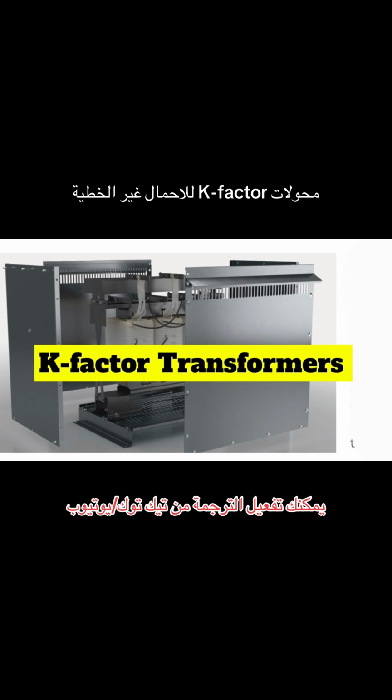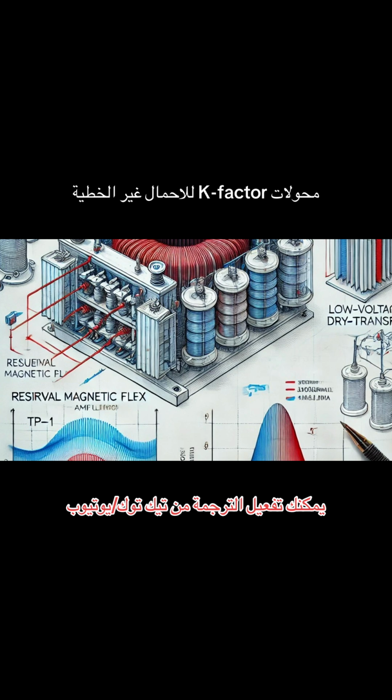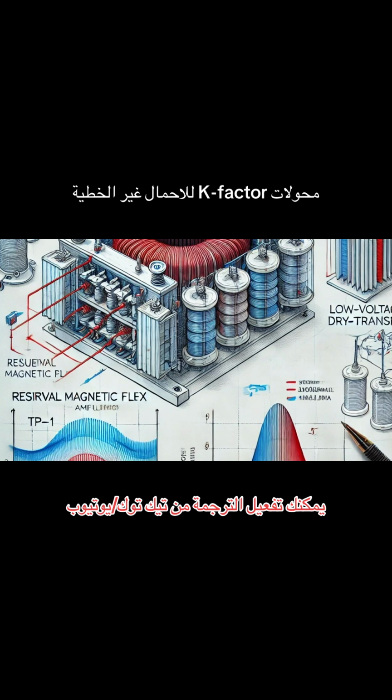You got it. Then we step up to K13. This is common in places like schools and hospitals where they have a lot of electronically controlled lighting. These systems can produce a lot of harmonics, and in these environments, you could have anywhere from 50% to 100% of the connected loads contributing to harmonic distortion. Wow, that's a lot of harmonics. It is. And then you have K20. This is typically for data centers packed with computer servers and for critical care facilities and hospitals.